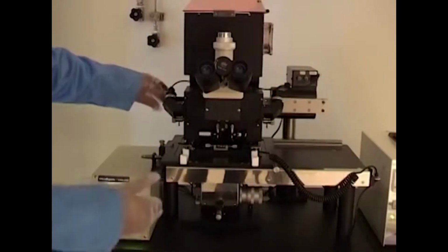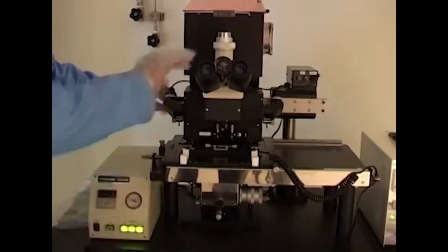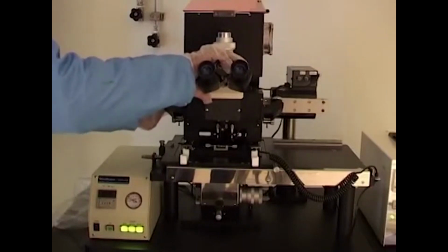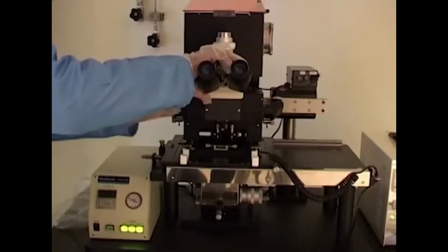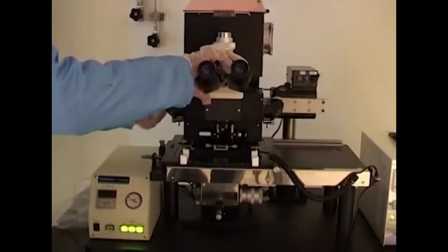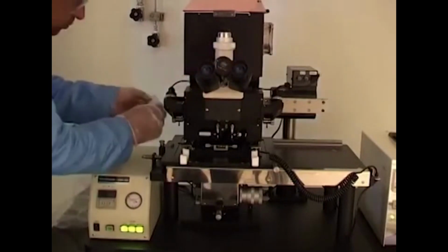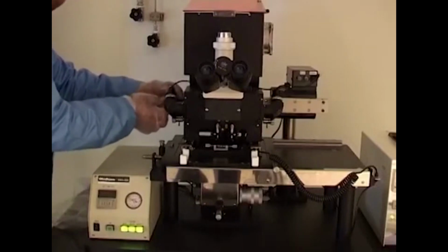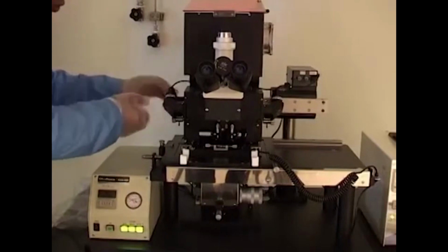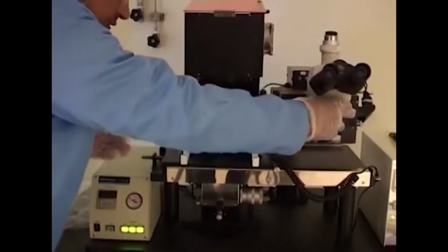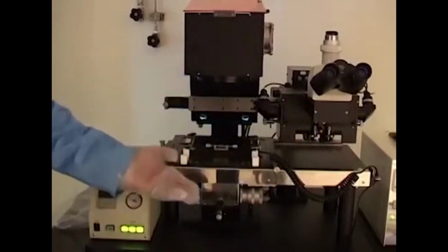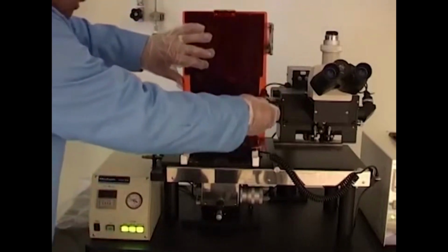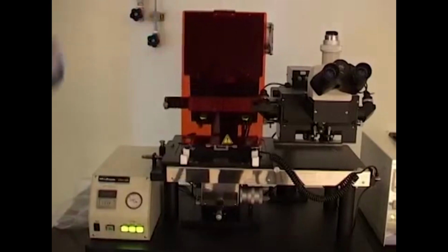Now, after all this exposure time setting has been done, we need to take care of this microscope stage by moving it back, because now we need to do the exposure. So I am going to unbolt this whole stage from here, shift it slightly towards the right and dock it in its position, and that is going to give me a through pass for the UV light to go through the mask and fall onto the wafer surface. So this is now taken care of. The mask is in contact with the wafer, and in order to protect the operator, there is a UV shield which has to be installed here before doing the exposure. We are all set to do the exposure.